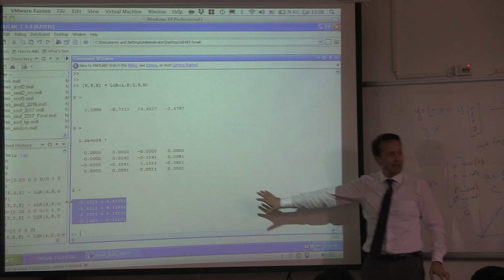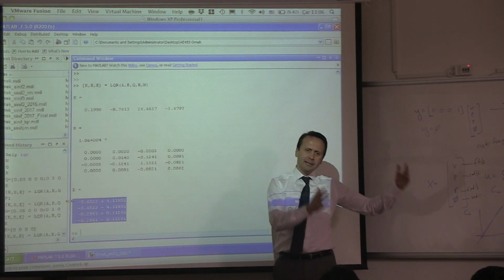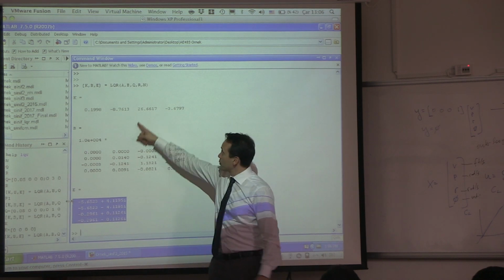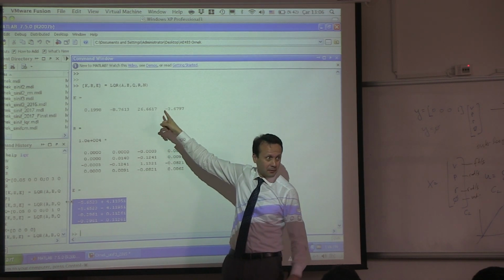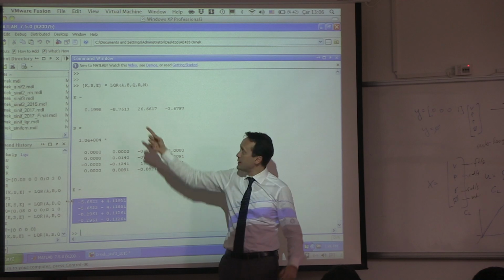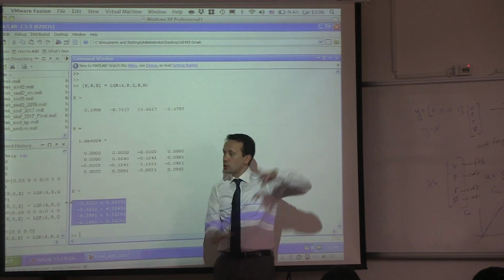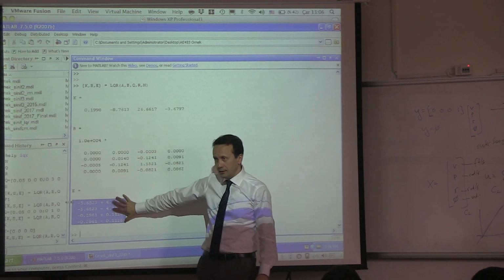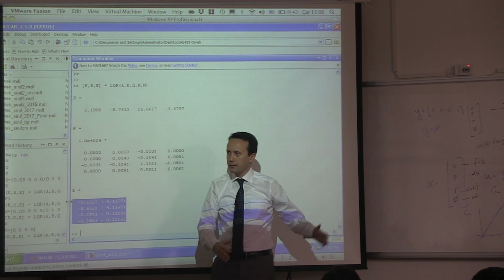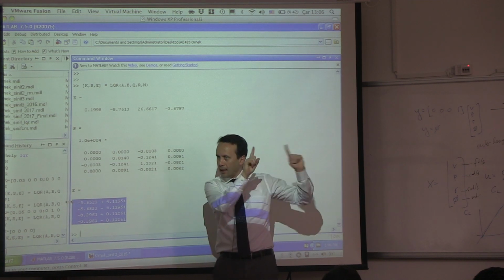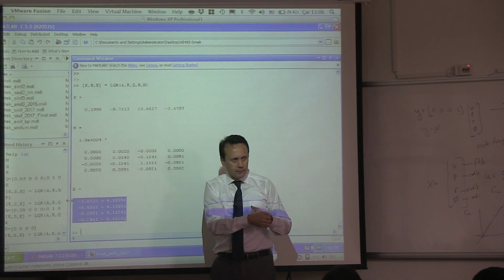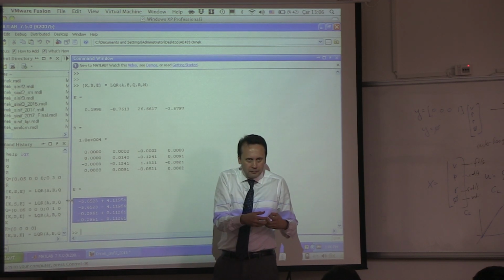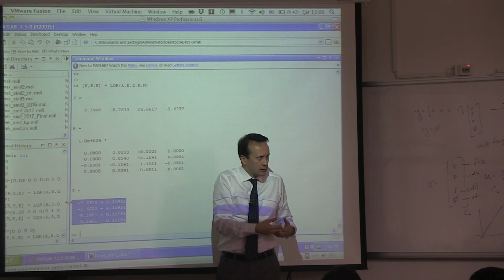You use that as the desired eigenvalues, calculate your integral gains, and those gains will change, of course. Remember, in the integral controller, you cannot first calculate that and then change the gains on the other side. You cannot do that. But since you know these ones now, you can go back and calculate the feedback gains and the integral gain together. Does that make sense? Okay, it's a little bit more involved, but at least you know what you're doing.